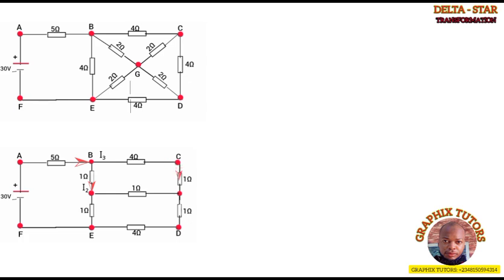Through the 1 ohm resistor, making 4 and 1 to be in series. Are we together? Now you can use R sub B to be equal to 4 plus 1 because they're in series, right? Similarly on both sides, this 4 ohm and this 1 ohm are also in series because the same current is going to flow through the 1 ohm and the 4 ohm.